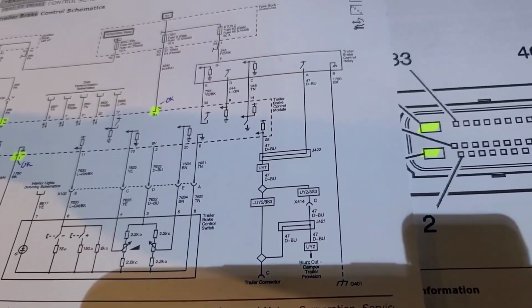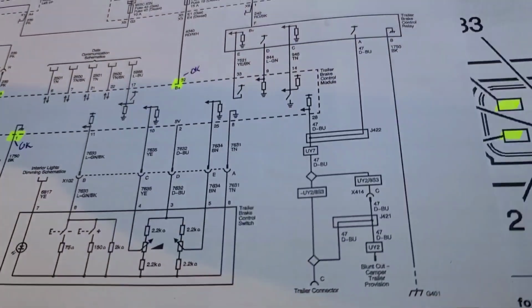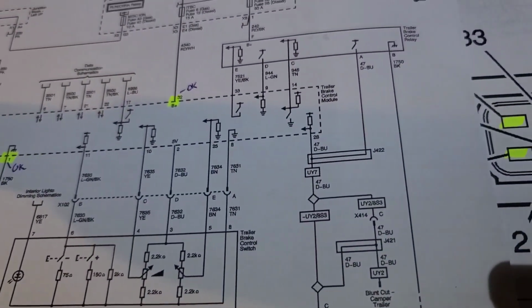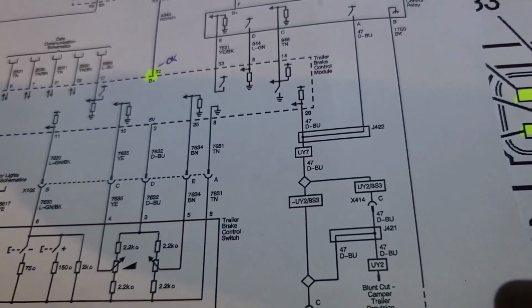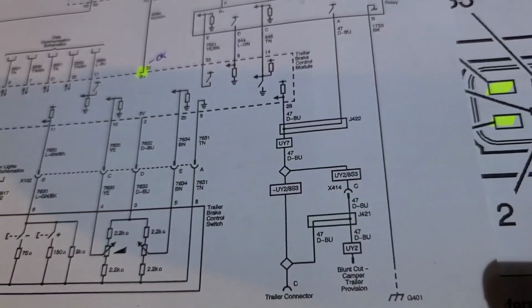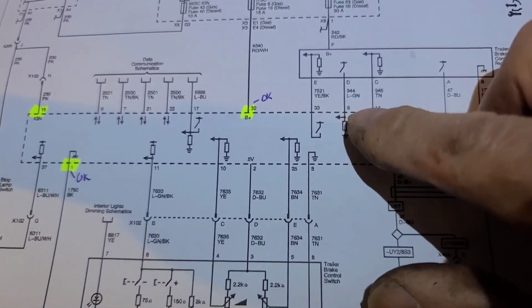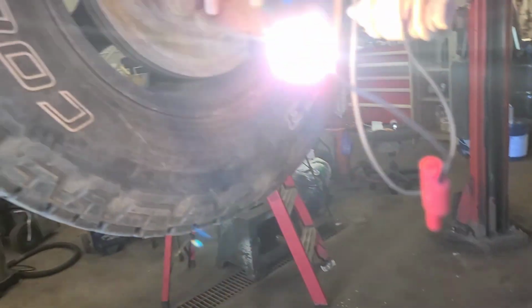So all of those wires test good. I jump power from pin F at the relay to pin E, D, C, and A. B is ground. And it shows up, that's on pin 9 now, I think. Yes, pin 9. This middle pin, the light green wire is 9. And it lights up a 500 milliamp bulb just fine.